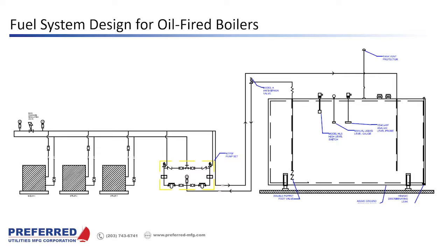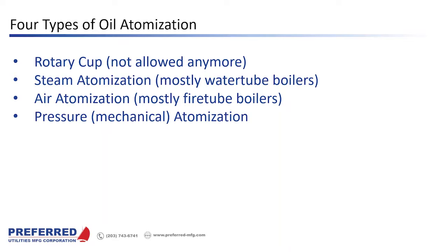Well, hydrostatic pressure alone for number 2 oil is 2.4 feet per PSI. So 2.4 times 3 is 7.2, which means you can't push oil higher than 7.2 feet without exceeding that 3 PSI limit. Forget about a back pressure regulator, forget about pressure losses in that pipeline. You can't even get the oil back into the main tank at 3 PSI. So we will return to this later, but if you take one thing away from this presentation so far, it's ignore that paragraph in NFPA 31. It's not applicable to boilers. And the paragraph includes an out for boilers. So anyway, moving right along.